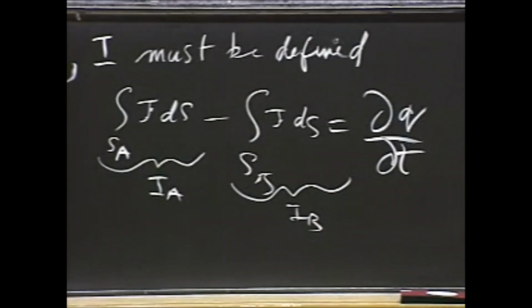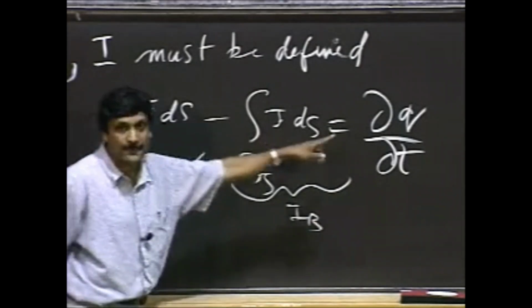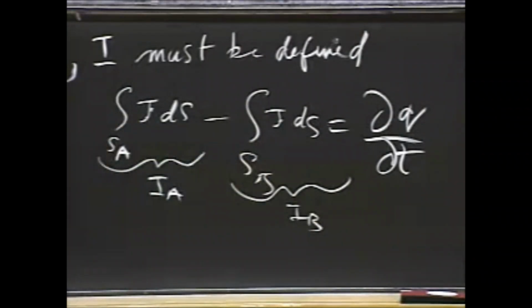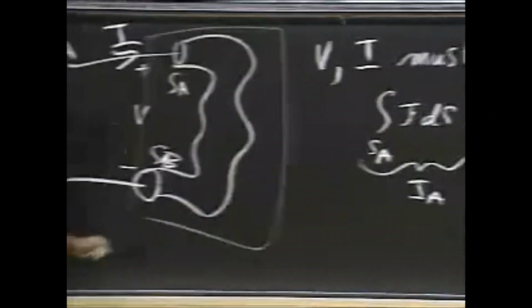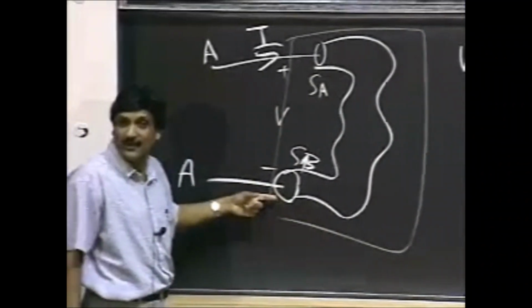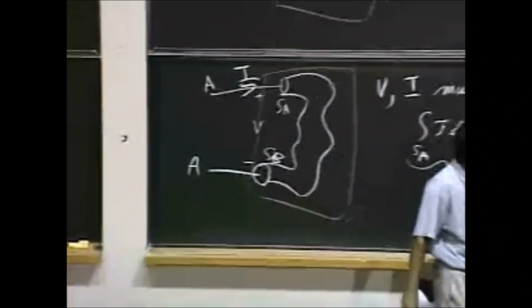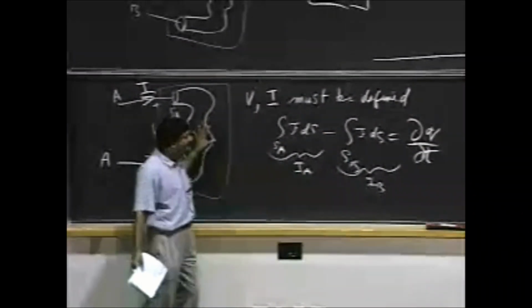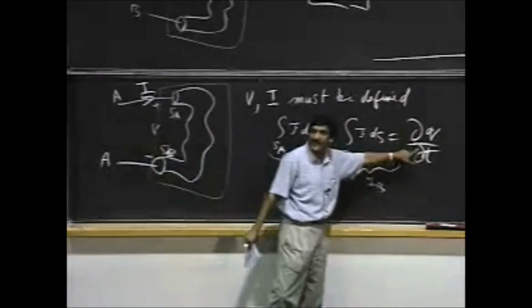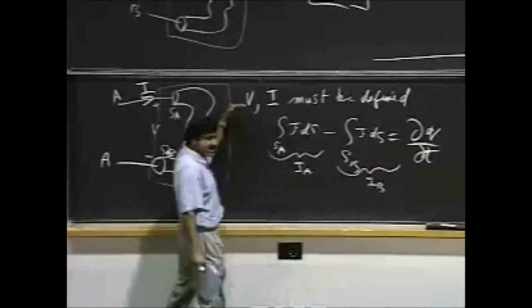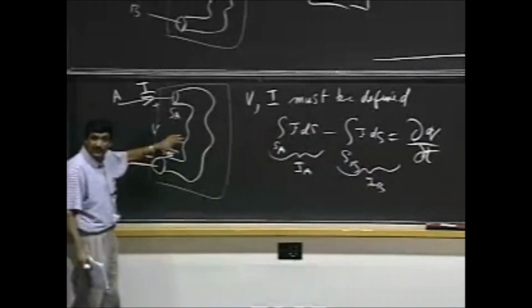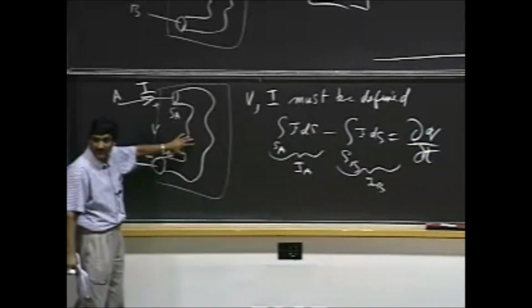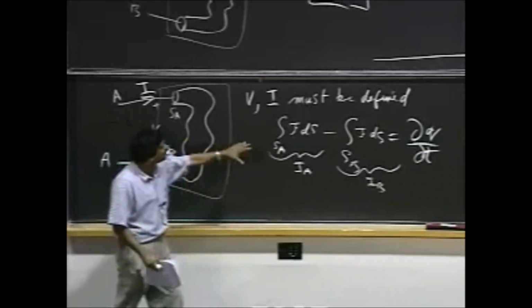But if I don't tell you anything else, you have to start from here. You might have some kind of varying current here by point. You might have some other current coming out here, because I may have some charge buildup happening inside. If charge was building up inside the filament, then I would have to put dQ by dt out here, right? The current in minus the current out must equal charge buildup. Whoa. Where's this and where's that?